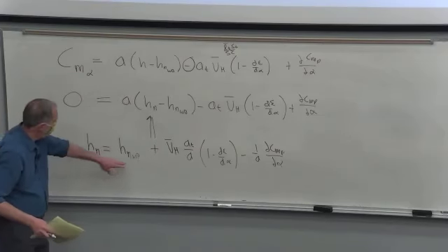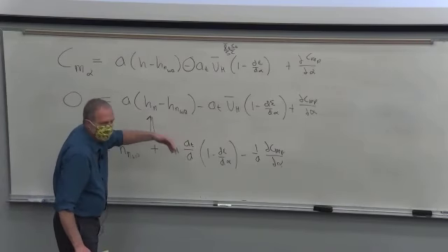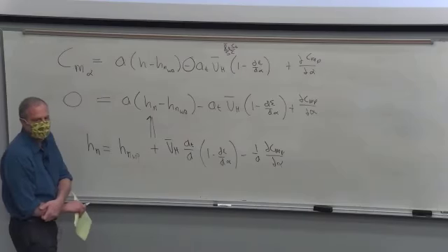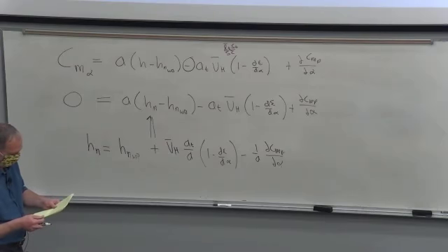You know where the aerodynamic center of the wing is, you know where your tail is, you know the lift curve slopes, and you can calculate it. That's really important to know for your airplane because then you make sure the CG is not behind that.